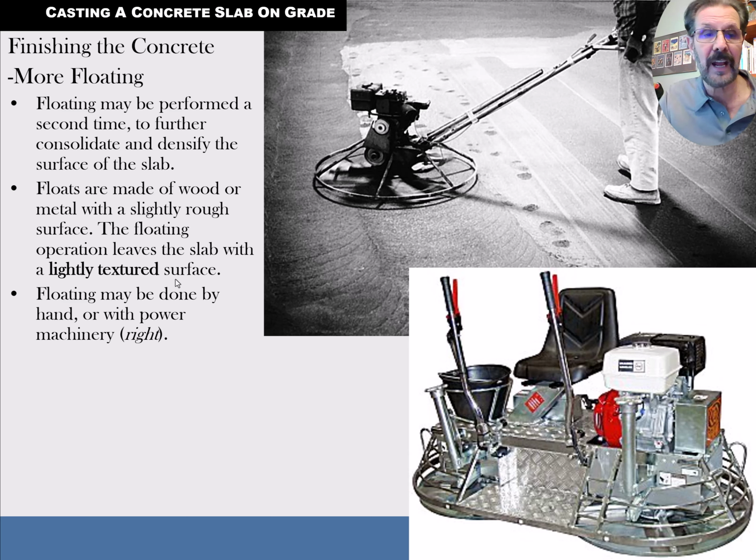And so inside a house, we don't need as strong a surface on the concrete generally, but we do need a flat surface for the flooring. We need it flat enough that any kind of flooring you're going to put down will be laid properly. That's an important function, but you certainly aren't making the concrete harder by troweling and polishing it. That's not what you're doing.